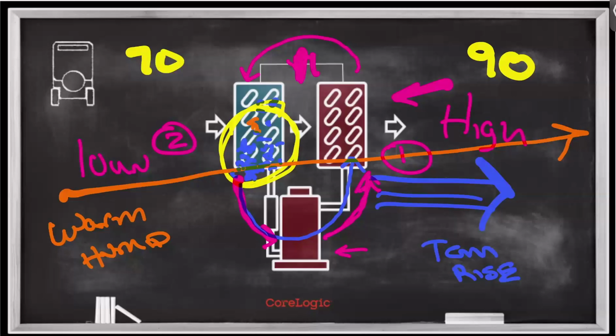In most dehumidifiers, this compressor down here is also adding a little bit of that heat, like 5, 6 degrees, maybe 7 degrees at most. But if you look at your dehumidifier and you have more than an 8 or 9 degree temperature rise, the dehumidifier is working. If it's working well, you're going to have a 15 to 20 degree temperature rise.